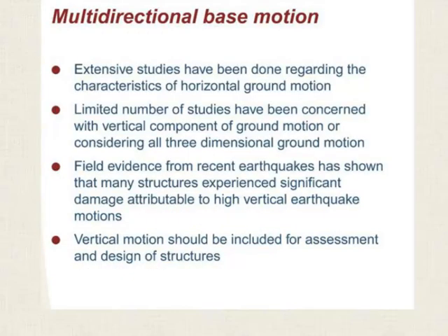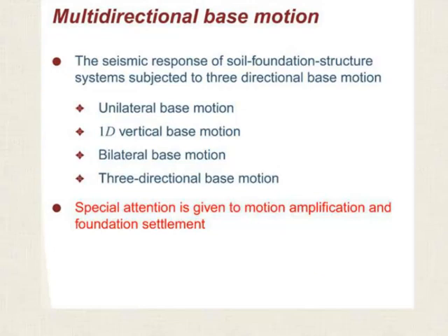With that, we are ready to tackle the main subject, which is to model seismic response, and we are accounting here for multi-directional base motion. There have been a lot of studies to tackle this problem, but very few accounted for the vertical component of earthquakes. So we try to shed some light on this issue using this technique. We perform a number of simulations. We start from unilateral base motion, and then we also look at 1D vertical base motion, and then bilateral base motion, and end with the 3-directional base motion.